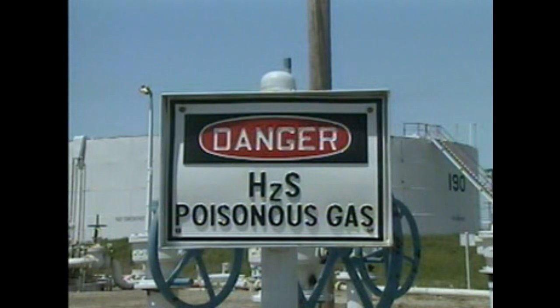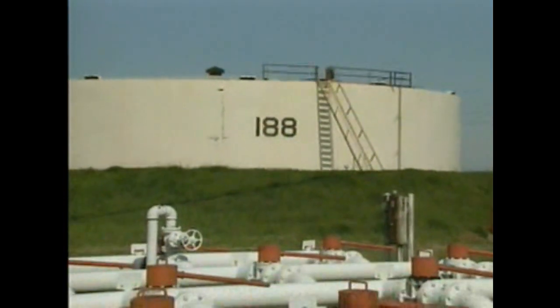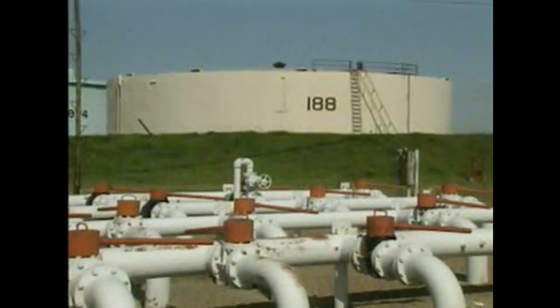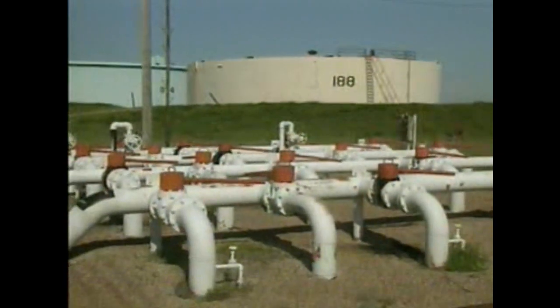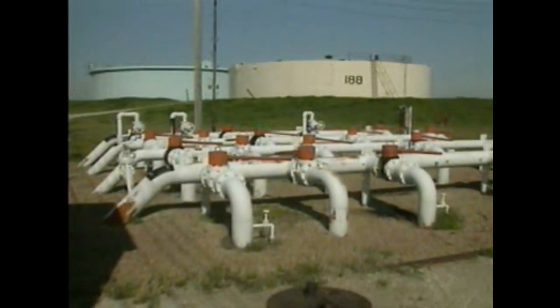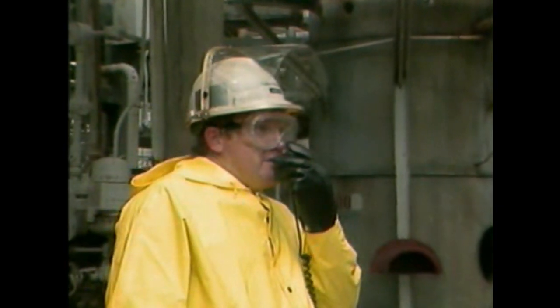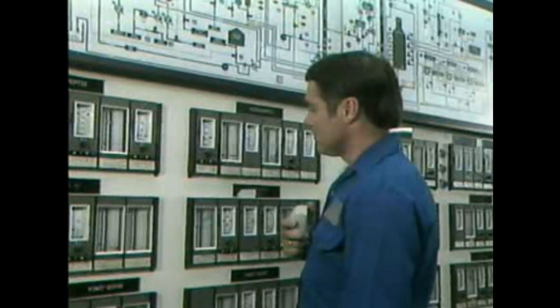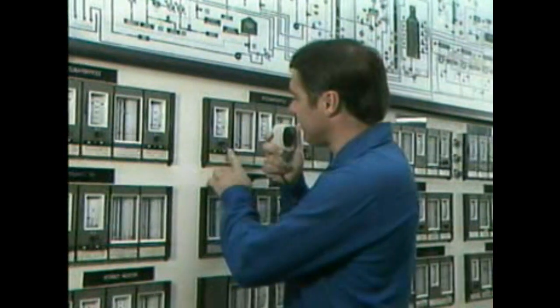The rotten egg smell of hydrogen sulfide gas can provide a warning that there's an emergency. While it's extremely unsafe to inhale chemicals to identify them, you may notice an unexpected odor. This is often a warning that there's been an uncontrolled release of material from a container, storage vessel, pipeline, or other area. In this situation, you should follow procedures in your company's emergency action plan.